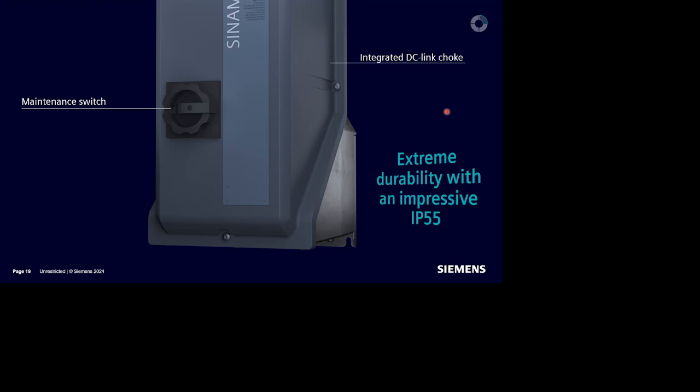In this case, the Sinamics G220 is a very robust drive, an industrial drive for continuous motion applications, also in the high overload. And if we take a closer look at the IP55, we can say that it offers extreme durability. Some of the options are, for example, the maintenance switch as an option. Also, the integrated DC choke. This is part of every Sinamics G220.